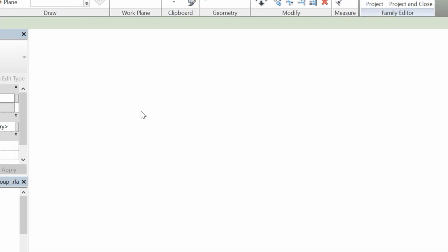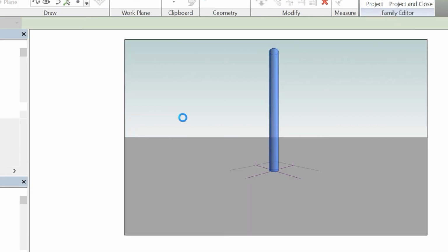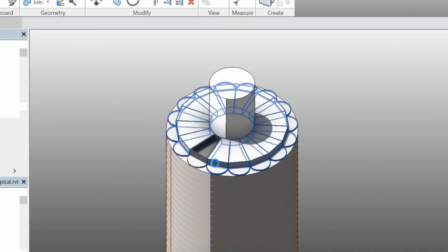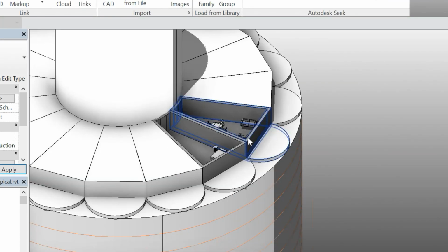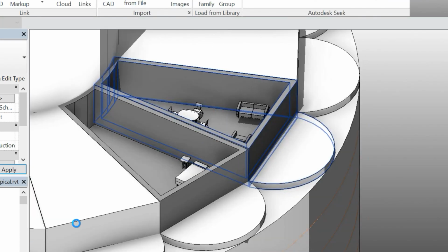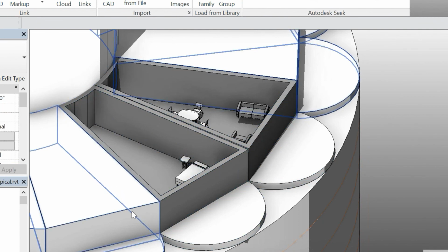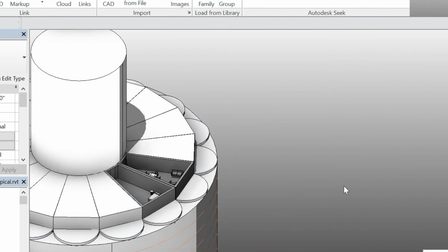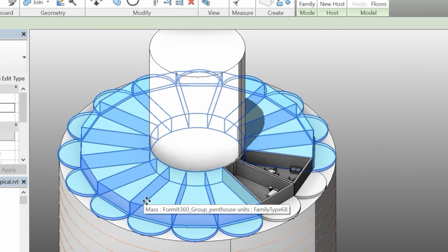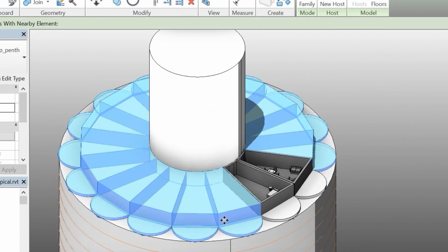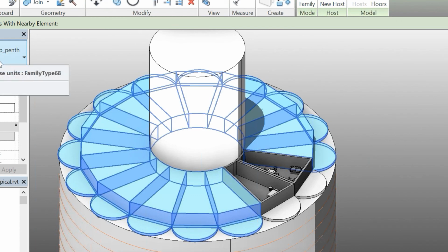So if I switch back to the project, that's a different one I was messing with. I'm going the wrong direction with my tabs. Okay, these white objects are all Revit masses, Revit mass families. And the other critical thing here is that I arrayed these 15 times. These arrayed objects are all mass instances. They are not individual blobs of geometry. These are actually mass instances of a family that's been created called penthouse units, because that's what I named the group in FormIt.